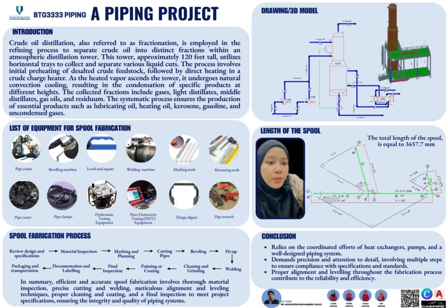On pipe 1, it has two joints, so the total root gap at pipe 1 is equal to 8 mm, and the width of the gasket according to class 300 is about 3.3 mm. So the total length of pipe 1 is 766.9 mm. For pipe 2, the length of the 90 elbow long radius according to class 40 is 152 mm.